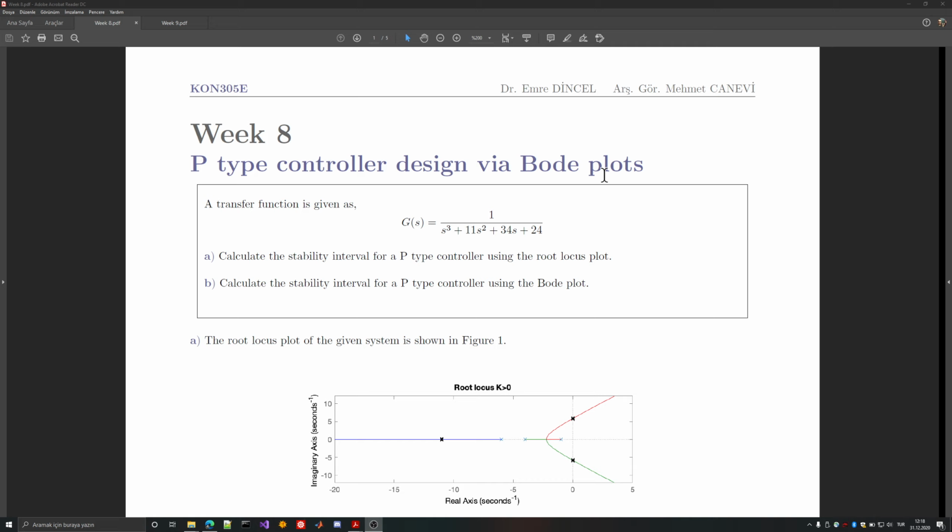You can use this given transfer function here, and if you plug in s equals j omega, then you would get a complex number that's depending on a variable omega, which is basically a complex valued function. And if you change omega in a certain interval, then you will get a continuous complex valued function, and you will have a real part and an imaginary part.